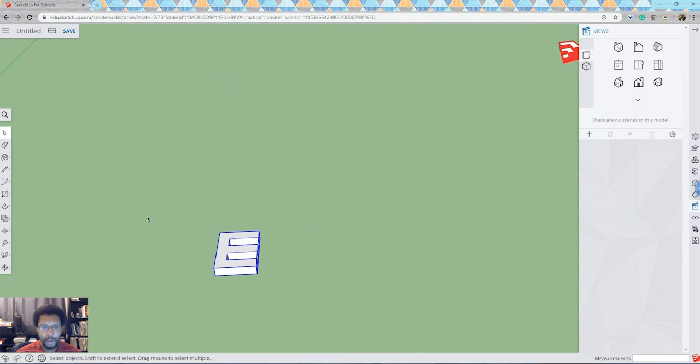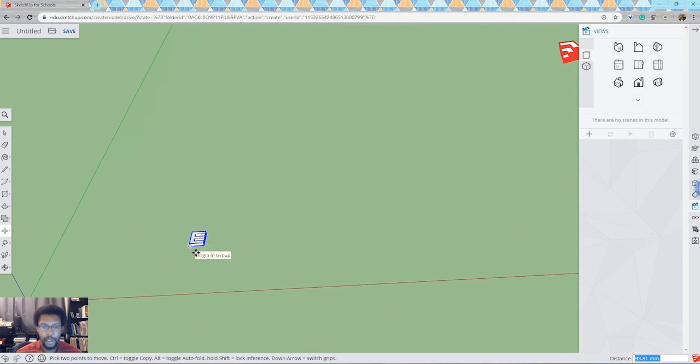It's a single object. And now to move it, we go down to this tool right here that says move, we select it, and we can basically select any one of the points on the object and translate it over to where we need it. So we can zoom out to make things a little bit easier. And then if you select, let's say, this back corner right here, you can move it and place it anywhere you want on the screen or in this 3D environment. So in our case, we want to put it at the origin, so we just move it to the origin.